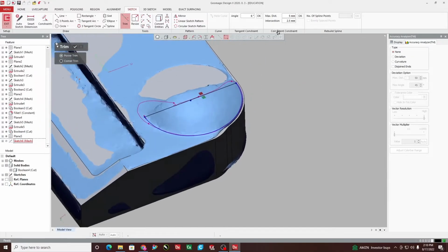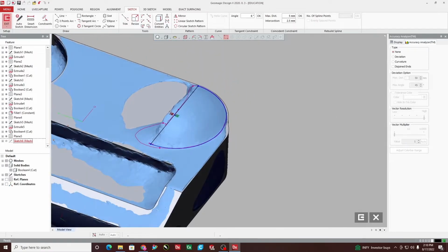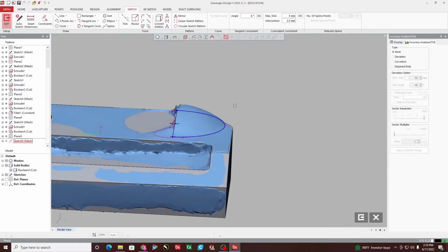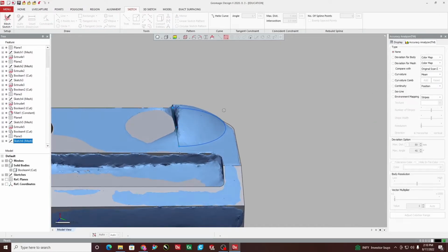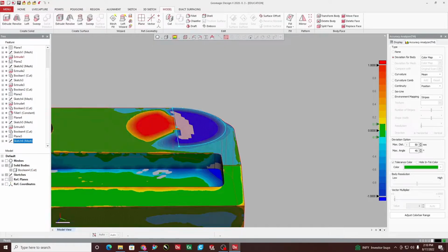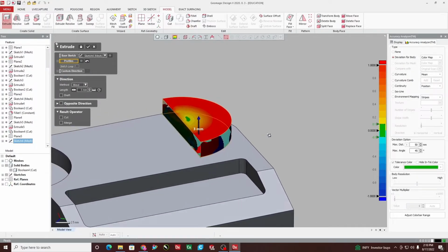So, we are now divided into 2 parts because creating a single circle would have been difficult to create separate dome and cavity dome. So, both of them will be taken separately. So, half circle is generated, that is semicircle is generated. So, now using the accuracy analyzer, we will see the height of the dome. So, taking the height of the dome and the circularity, we have to keep matching it using the accuracy analyzer.